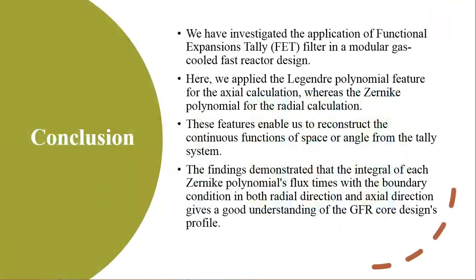We go to conclusion. We have investigated the application of functional expansion tally filter in modular gas fast reactor design. Here, we apply the Legendre polynomial feature for axial calculation and Zernike polynomial for radial calculation. This feature enables us to reconstruct the continuous function of space or angle from the tally system. The finding demonstrated that the integral of each Zernike polynomial flux time with boundary condition in both radial and axial direction gives a good understanding of gas-cooled fast reactor design profile.